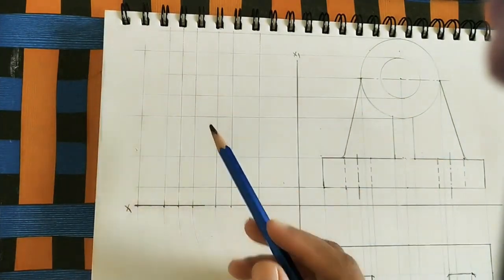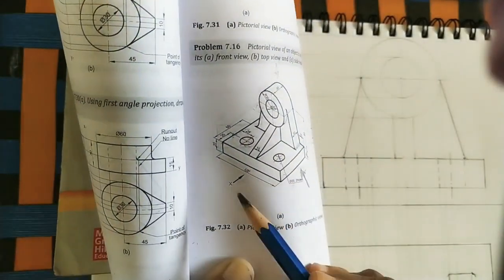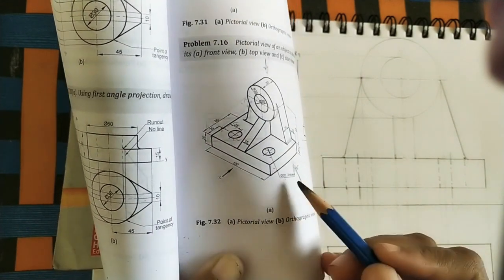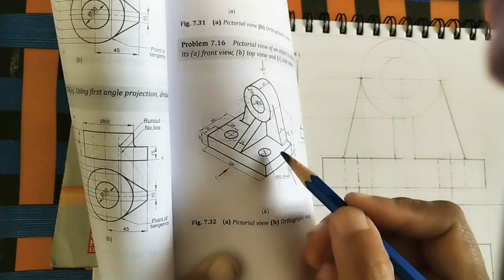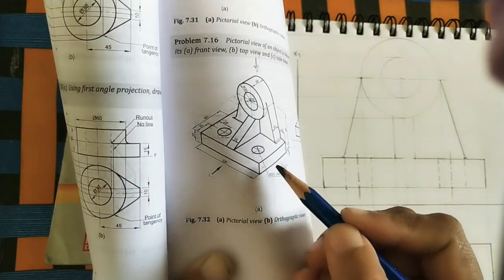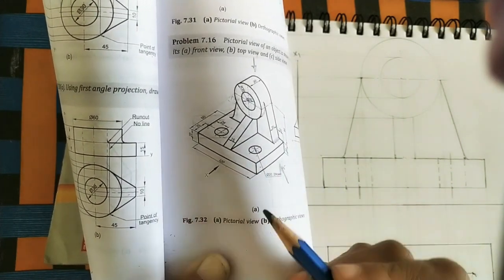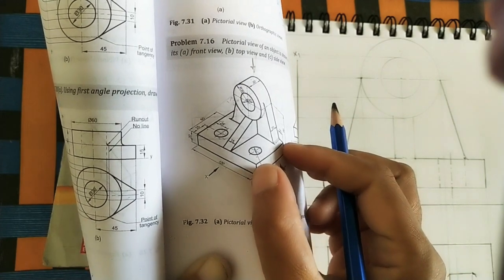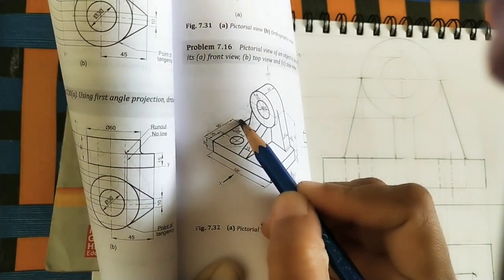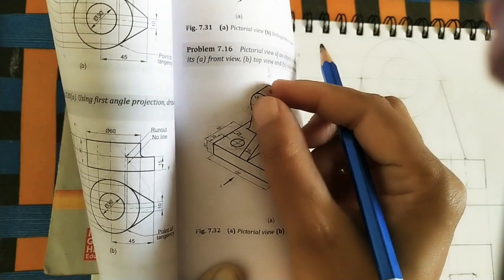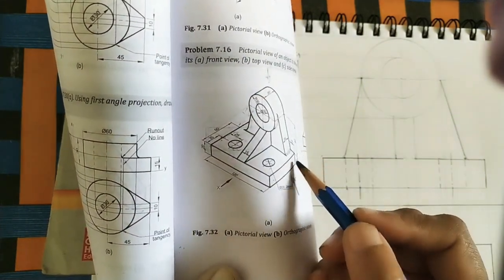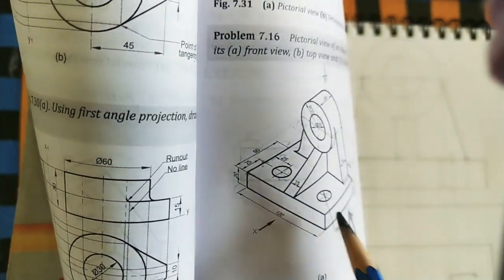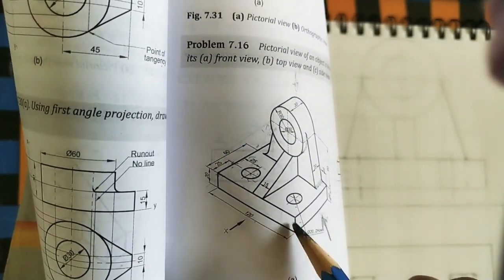Let us do the side view here. For doing the side view, as I already told you, whichever direction the arrow points to is the front view. The next side, where we can see the entire side, is called the side view. So this is the side view part. In the side view, we can see this rectangle initially, correct? How much width is it? I already told you, 60 mm plus the remaining part is 30 mm. 30 plus 60, completely 80. So 80 by how much thickness? 20 mm. Throughout this block it is 20 mm. 20 mm by 80 mm.